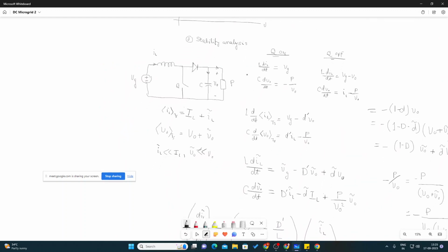And hence I am coming back to your first question, that is, why is there a resistance. We place a resistance in parallel with this. So when we add a resistance, what do we have here? We will have minus P by V naught minus V naught by R. I am writing it with a different ink. So these are the changes. So this will be minus V naught by R.